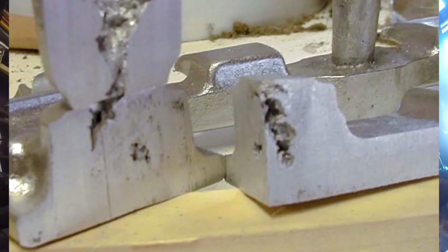This next picture shows examples of what happens when you either don't put a riser on a casting, or you design it incorrectly. All right, the right hand side may not have even had a riser, I'm not sure, but if it didn't have a riser, that's the reason for the shrinkage that took place inside in the middle of the metal.